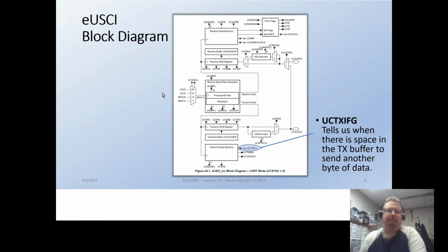I'm getting the feeling that you can't really do serial communication without interrupt vectors and stuff. Well, you can indeed do polling. And at slow speeds, and if you've got the horsepower to spare, then polling is fine. I do it occasionally, depending on the application. In a medium performance system, you definitely want to have some interrupt mojo happening. But if you want truly high speed, then you're going to use what's called DMA, which is direct memory access. And that's really cool when you get it working.